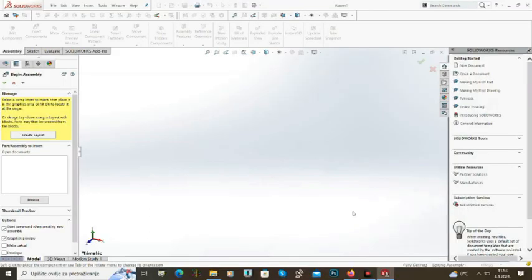Now the next technique that I'm gonna show you is top-down assembly. So what is the top-down assembly? So this is completely opposite that regular assembly, because in normal regular assembly, you create a part 1, part 2, part X, then you create assembly file, and then you put those parts into that assembly file. But this is not what we want to do. We want to go directly to the assembly file and we want to create parts in the assembly file and then define the relations between those parts, okay? And this is the approach called top-down assembly. It's much faster, okay? So let me show you.